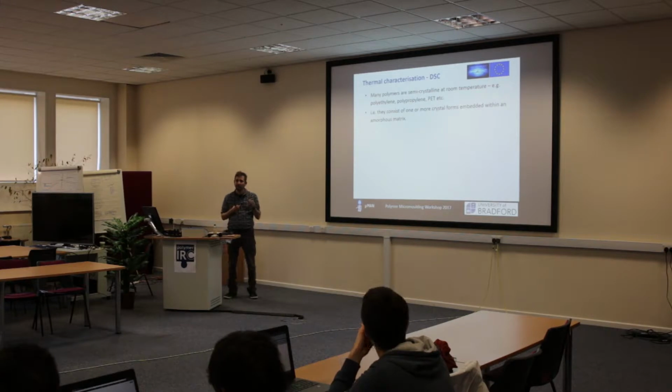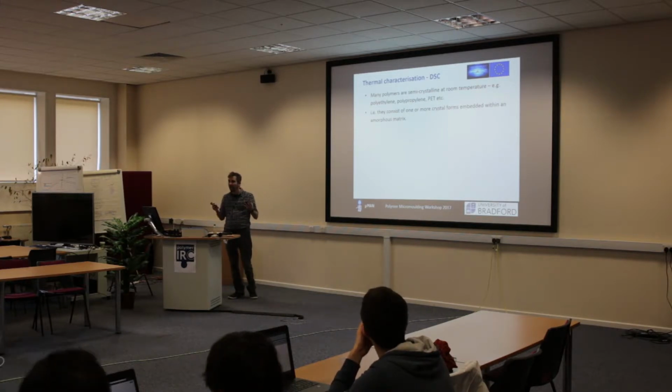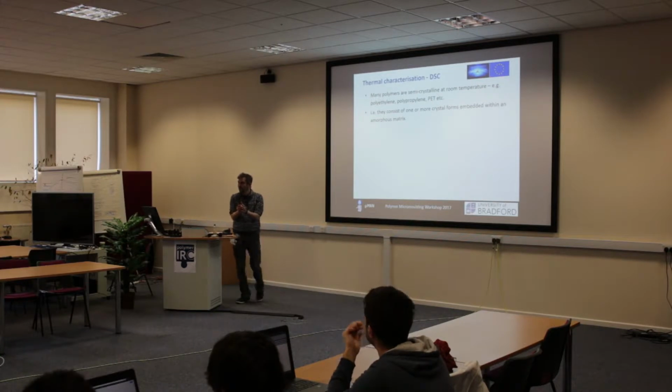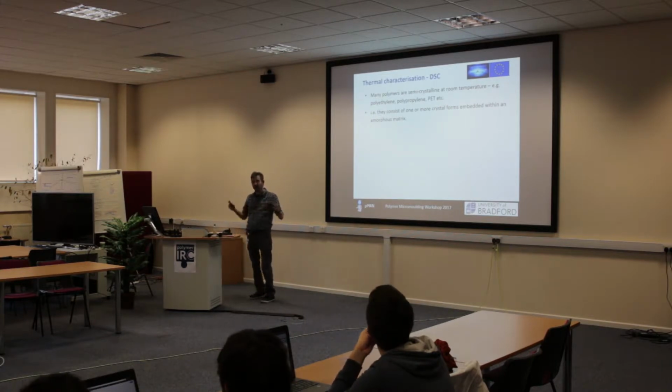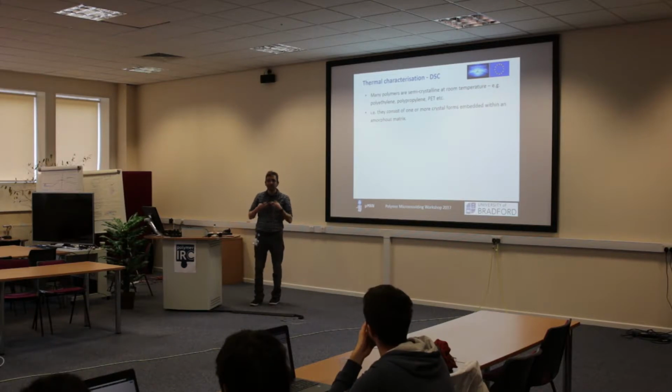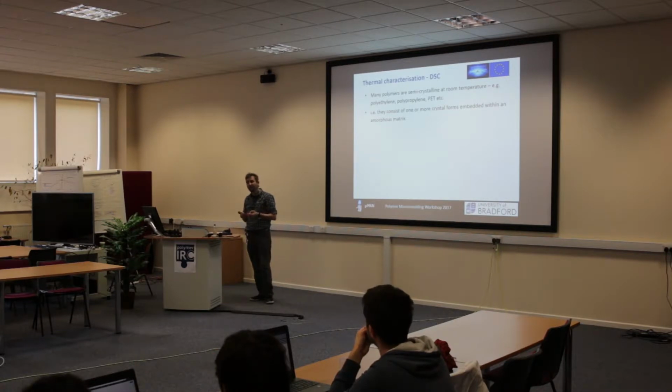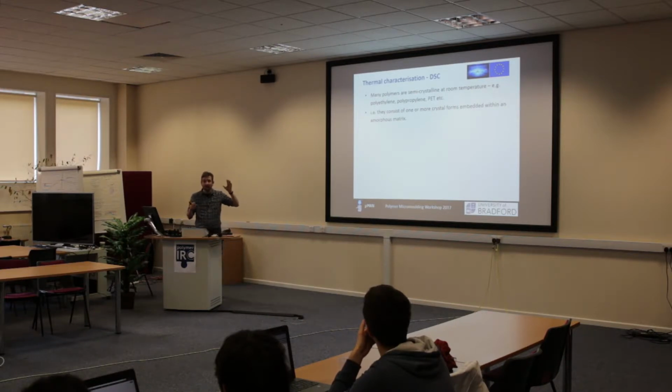Now, some of these crystals will be very strong, and generally, thermodynamically, that's what the material wants to produce. However, it's not always the case. By putting in process history, by heating, cooling at different rates, by putting flow in, you can change the crystal form. And so you may end up with lots of crystals, but they might be very, very weak. You can end up with twisted crystals, which are phenomenally weak, okay? And will give you wear problems and give you impact strength problems and all sorts of things, okay? Despite the fact your crystallinity still looks quite high, okay? So it's not enough to just say, right, high crystallinity means strong part, basically. That's not always the case.